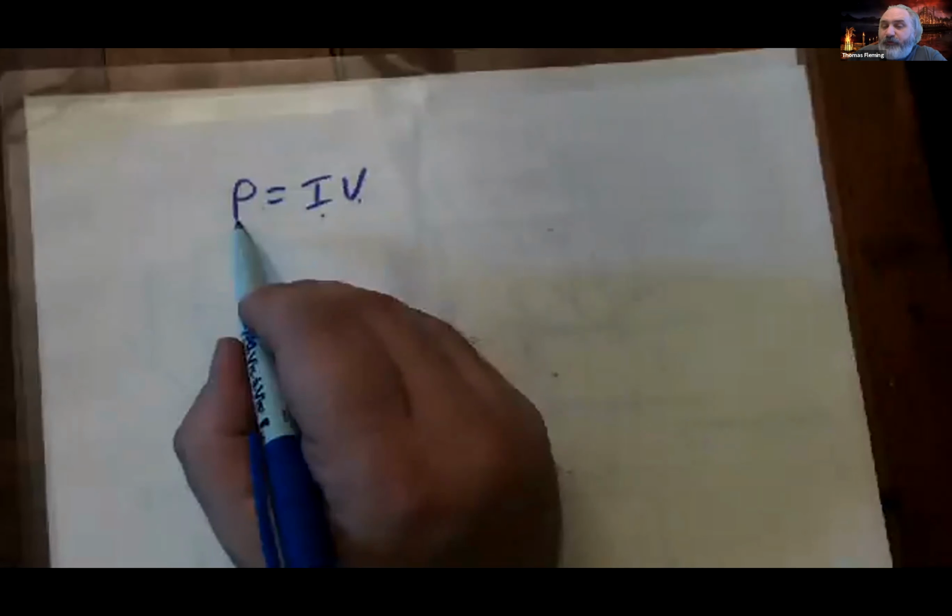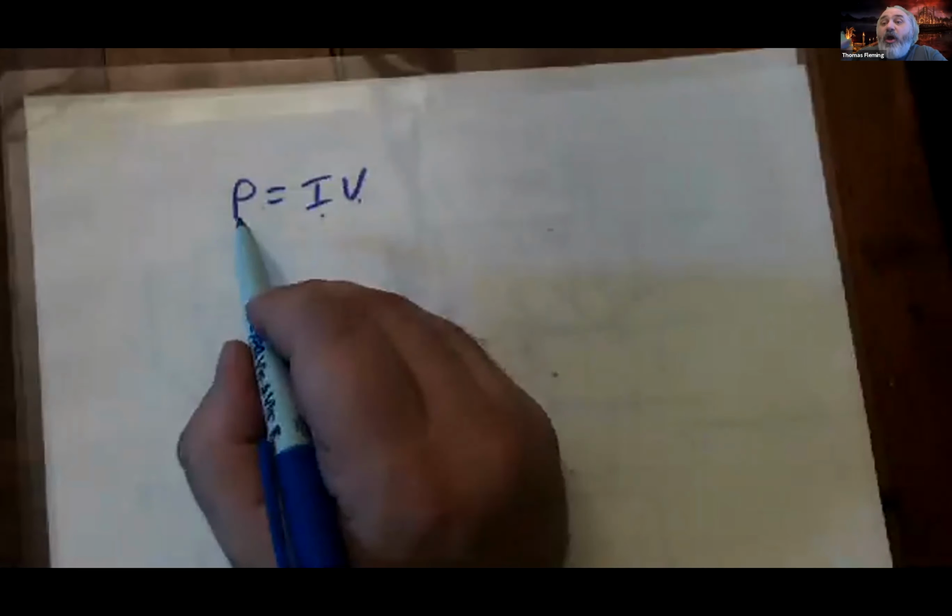So if you want to maximize how much power you're delivering to your circuit, then what you want is for the moments when you have lots of electrons coming out of the battery to also be the same moment that every electron has a ton of energy. So the power delivered in an AC circuit is going to depend on the phase angle.